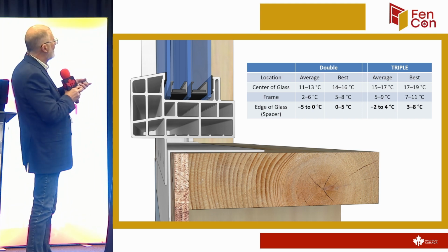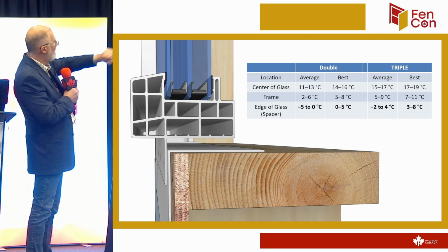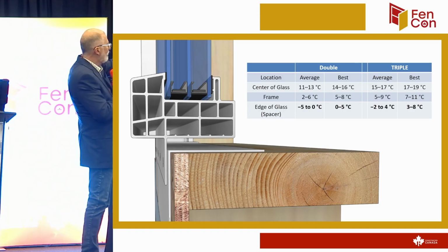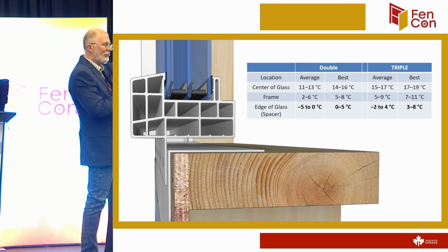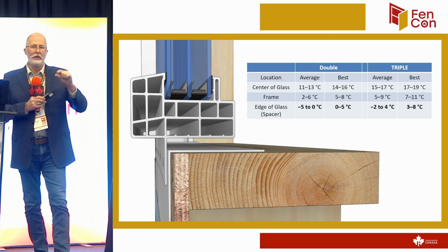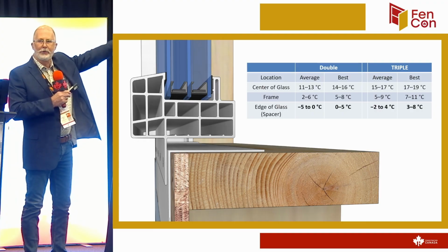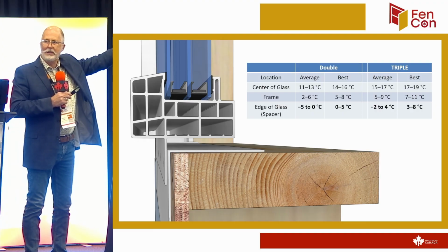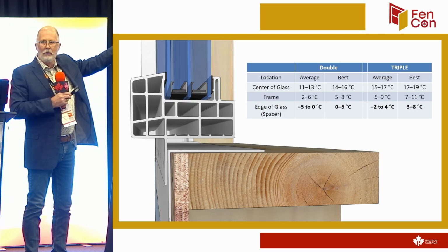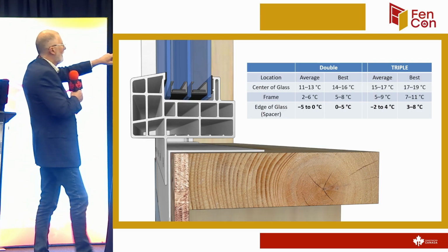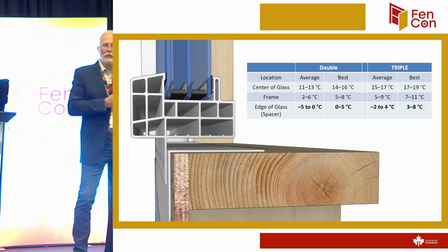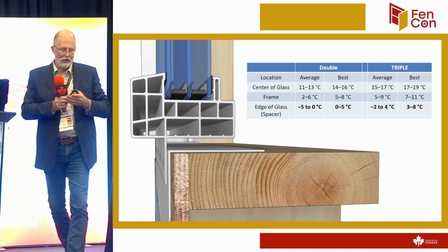What about the frame? Look at the temperature difference from the frame. Center of glass is one number. Frame is another number, but look at the edge of glass difference. So that's where you're going to start to see the buildup. So the argument that removing the insulation in the rough opening doesn't hold true to the science of where the temperature differences are on an actual window. Plus, if you look at the ability of that window to absorb heat, that thermal conductivity, it'll warm up really fast just by showering a little bit of air over it.